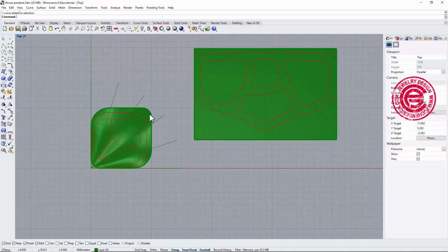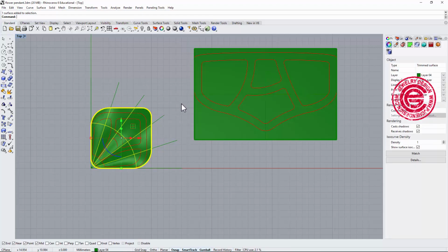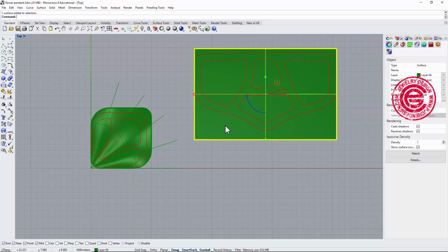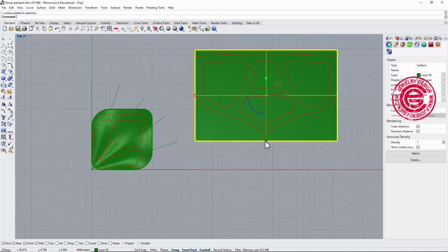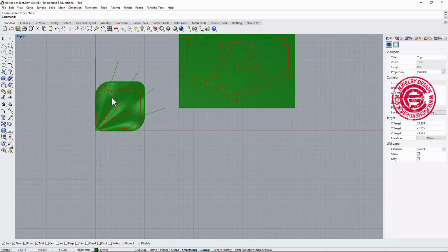The reason it is shrinking is because this surface was cut out from a bigger surface. Remember that we used the loft to create that. So this surface is actually the bigger one. The big rectangular surface is the bigger surface before we cut it. All right. So in that case, it is reading the distance between this point and this point, which is the distance between here and the edge. Okay, so it doesn't flow accurately there.